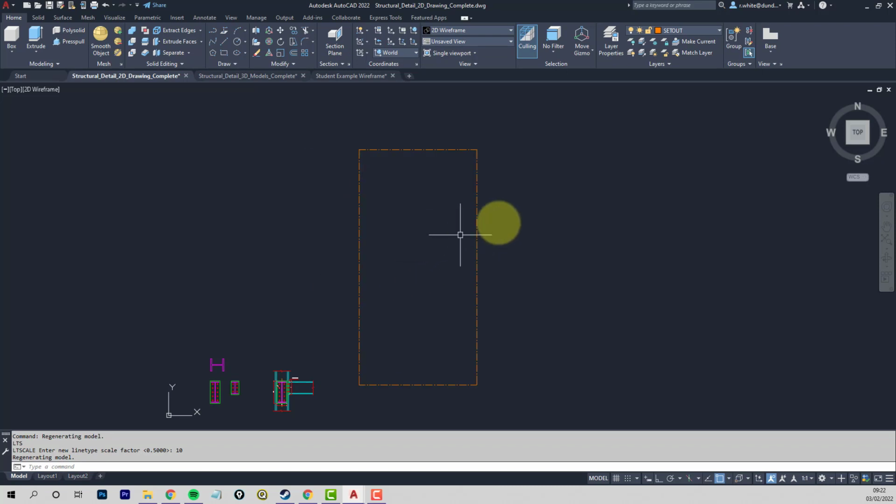Okay, so the first 3D operation is to view this from above, and we generally want to be from the side as well as directly above. There's all sorts of ways you can do that. We've got these gizmos on the right hand side here. This is called a view cube. It doesn't look like a cube at the moment until you click a corner.